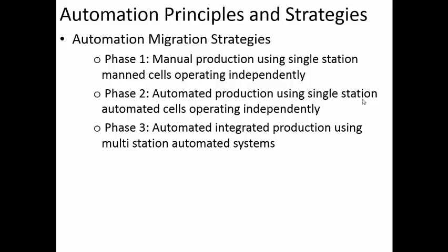Thereby we are able to meet the demand. Now if the demand is not there, there is not much of a loss, because whatever equipment is there is still conventional equipment. We can produce some other component using the same equipment. But if you procure a CNC machine, the number of components that can be produced is very limited, because the machine was selected to produce a particular set of components. It will have its own limitations. A general machine has more variety possible, whereas a CNC machine has some limitation and less choice available.